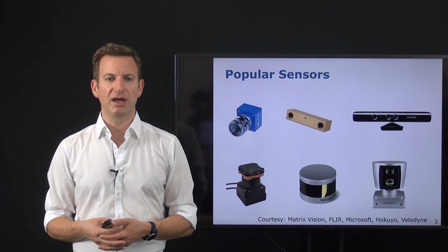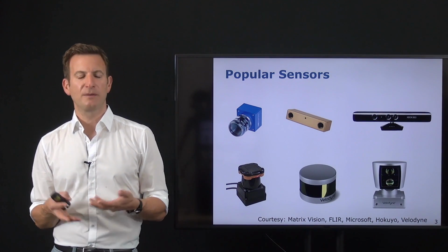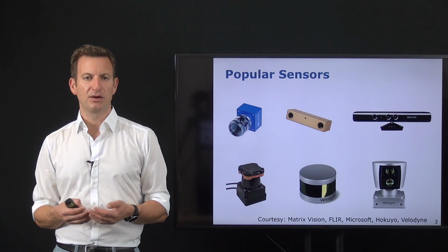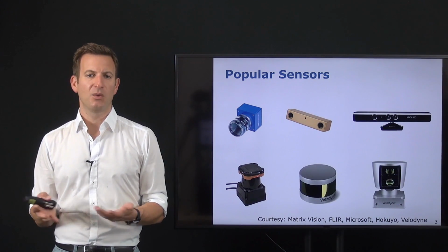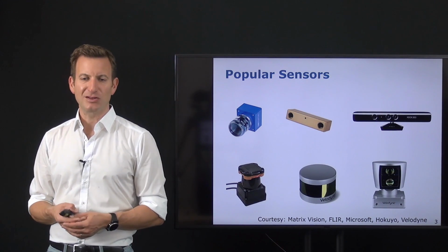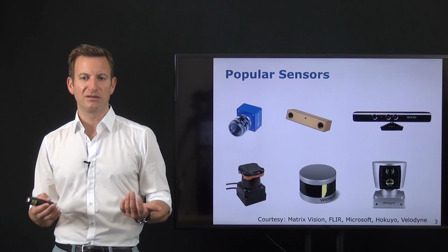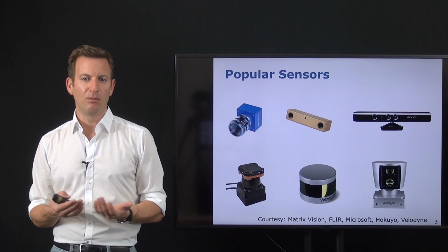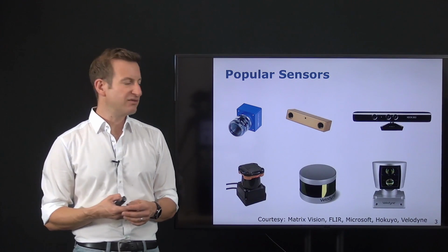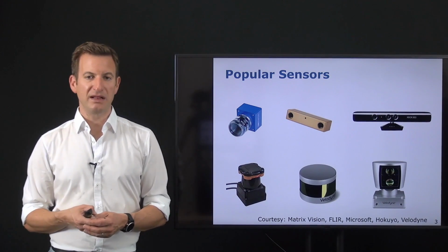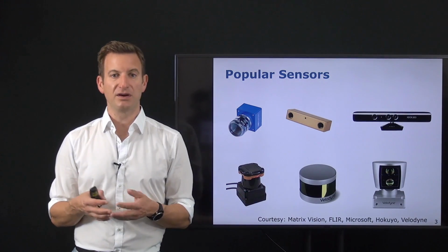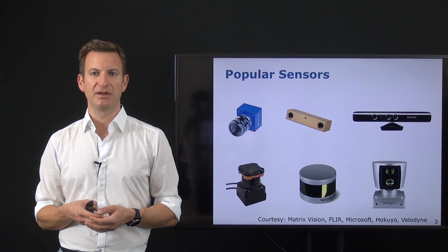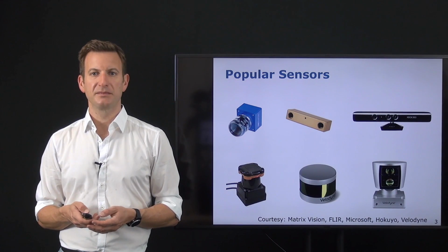So our assumption here today will be basically that we have a range sensor, and we do two small examples with that. One with a sonar range sensor, something which is a little bit outdated technology, at least on robots that are out there today, which typically use higher quality sensors, unless it's a very cheap device. The second example will be a laser scanner, something like this over here. So we will look into the question of how to build a map of the environment with such a laser scanner.